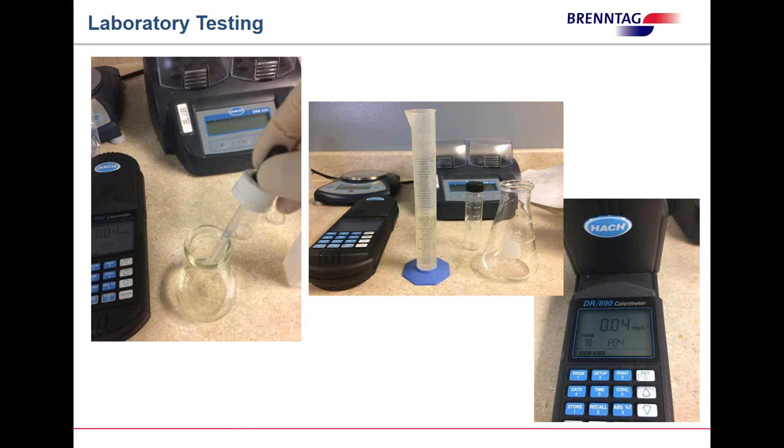On this particular colorimeter, I can hit a concentration button, and it will automatically do the conversion to the actual total phosphorus as phosphorus. If you don't have that, you can simply multiply the result by 3.27, and that will give you your actual phosphorus. Next.